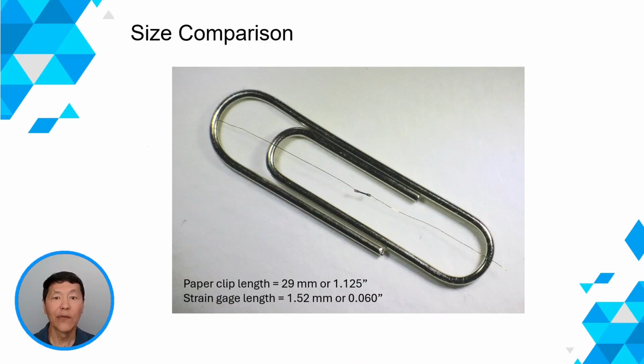With standard foundry methods, feature sizes on the order of 2 micron are easily attainable. Here's a photo of a semiconductor strain gauge that is on top of a paperclip. The gauge measures 1.52 millimeters or 60 thousandths of an inch long. The paperclip is about 19 times longer than the strain gauge. Piezo-Metrics installs many of these gauges into high sensitivity, high stiffness transducers.